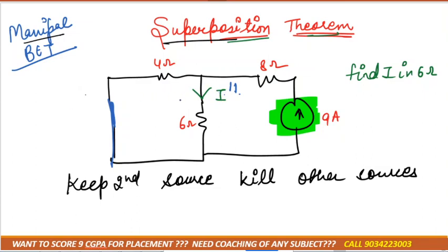So now in this case you are having again two options. You can apply KVL, KCL or CDR. So in this case current division rule would be much easy for you if you know about it. Current division rule is like we can directly apply the formula. I double dash would be equal to total current. What was the formula for that current division rule?